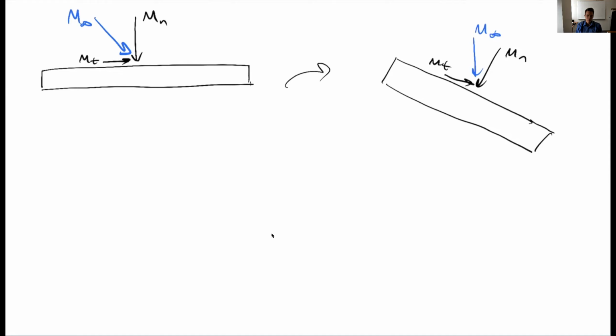So that's been a big revolution in air transport. Okay, so that's what we'd call transonic wave drag. The reason why we call it transonic, that just means near sonic. Although the cases we've been talking about are really sort of subsonic, that's often what we refer to as the transonic region, somewhere in, say, Mach 0.6 up to Mach 1. Sometimes for transonic we say above it, but supersonic, by definition, means above the speed of sound.